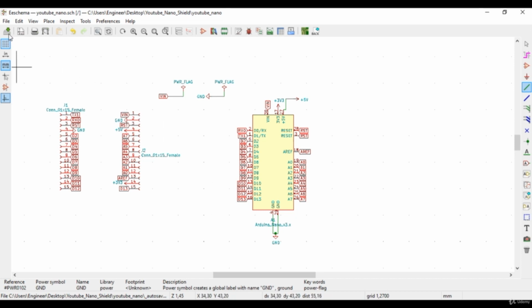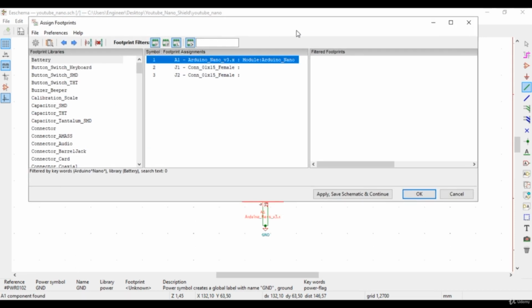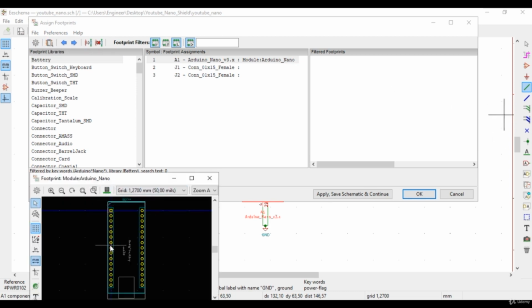Yes, first, let's save our circuit. We click on the icon that looks like an op-amp or integrated. I call it Assign PCB. Yes, friends, the footprint assign screen has arrived. When determining footprints, I also look at their 3-dimensional version. In this way, I minimize the chance of making mistakes. You can view from this section. This is how I positioned my screen. You can also view the 3D image from here.